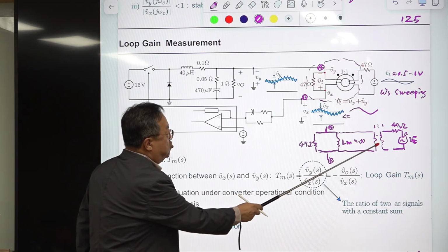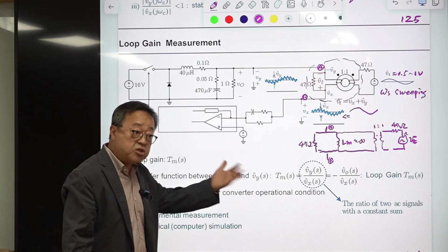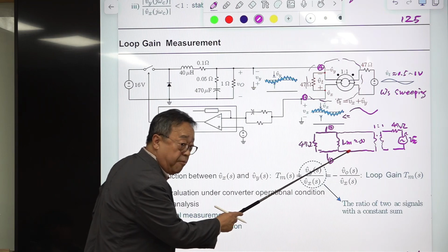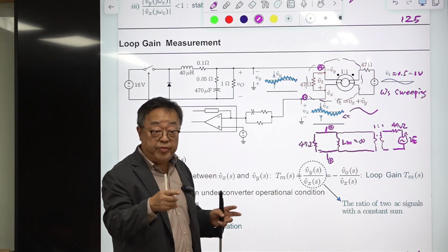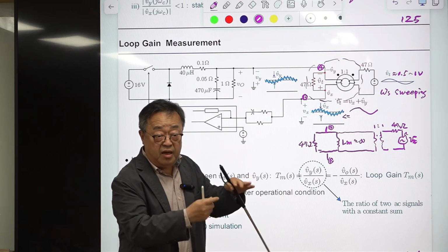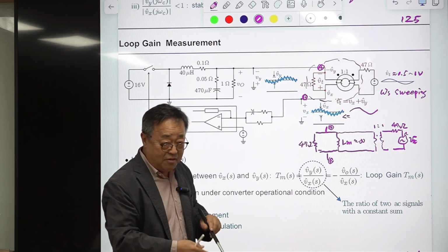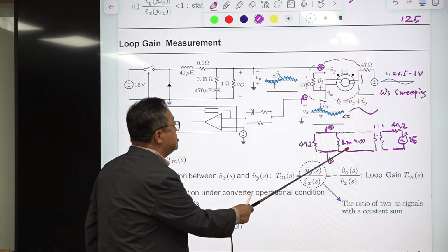And this is the 1-to-1 transformer. You've got to use a big transformer with large window area to increase RM. You need something like PQ 50-50, the largest one, and maybe 100 times like that. That's the extreme example, but increase this and this.